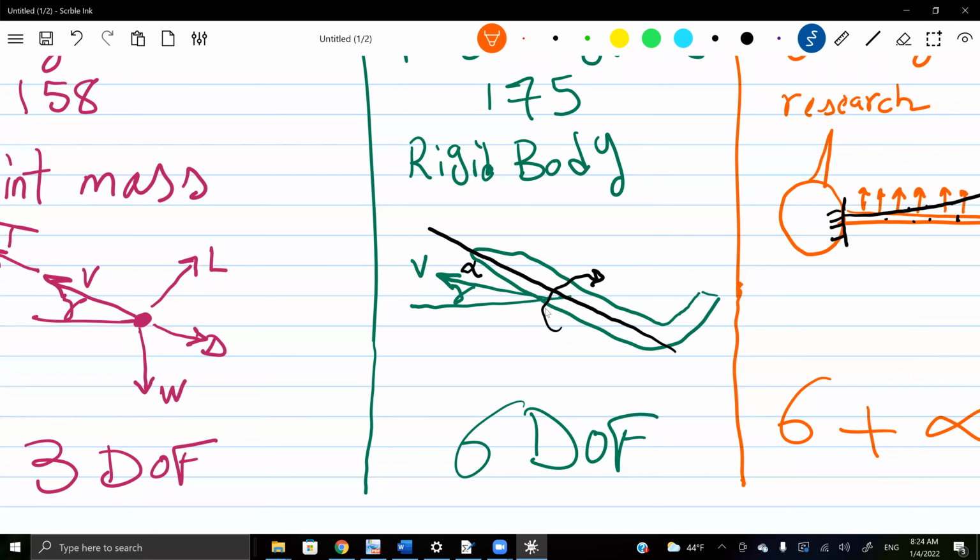What do we mean? When the pilot pulls the stick, so tries to command the airplane to climb, all right? What he or she actually has at his or her disposal for control is to rotate the body, okay? Rotate that black axis of the body. It's as if you're holding the body and you're rotating it. Well, you have no control over rotating the velocity vector.